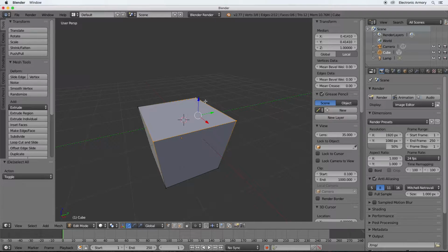Let's hide the manipulator tool for a second. Press the button on the bottom that looks like an axis. This will hide the manipulator tool. I usually keep this off anyway since it just gets in the way. Keyboard shortcuts are faster anyway.